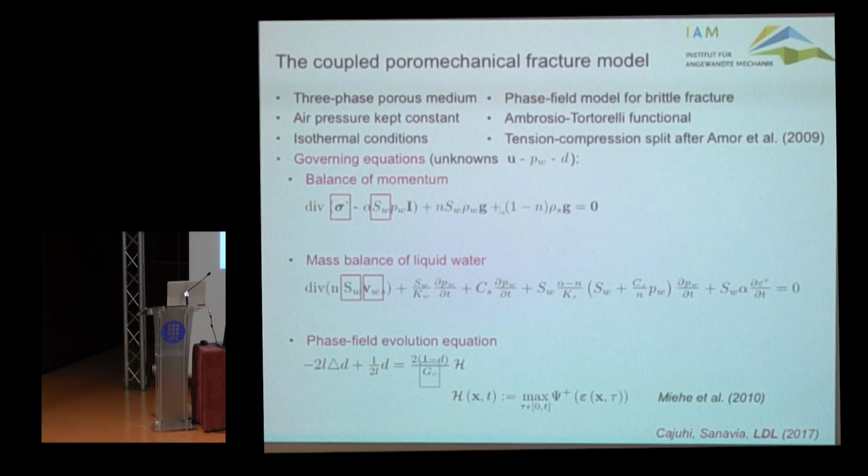You see here we are using the so-called effective stress concept, which is very well known to people working in porous media. This is the saturation. This is the relative velocity between the fluid and the solid. And in this case, you see in the phase field evolution equation, the fracture energy GC is also in a box. A box of different color, but still a box, because it will also be expressed by means of a constitutive law that I'll show you in a second.